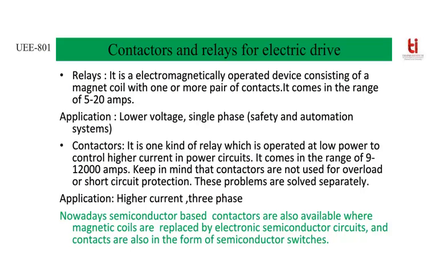One thing to be kept in mind is that contactors are not used for any protection, such as overload or short circuit protection. These are just used to give a path to the current. When it is closed, current will flow through the circuit. When it is off, it is open, and current will be blocked. So overload or any other protection is to be handled separately.